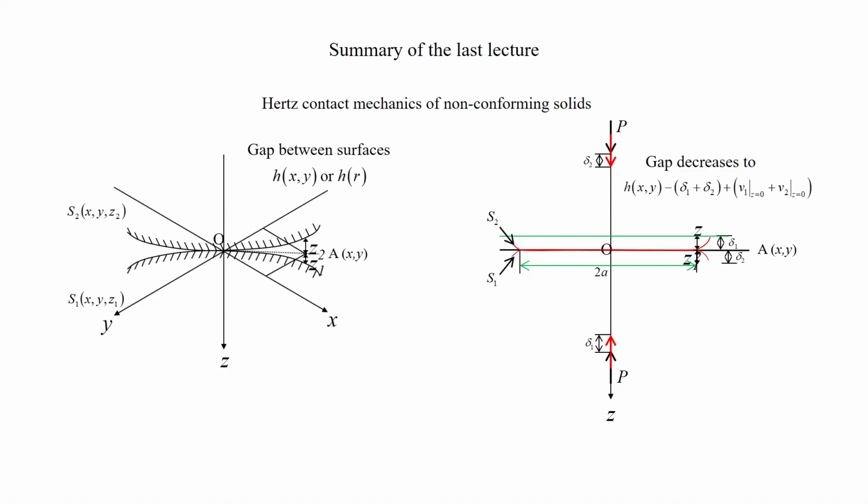In the last lecture we talked about Hertz contact mechanics, and today I will briefly recapitulate what we spoke about yesterday in the last class, and then we will discuss some ideas about surface energy and adhesion and surface interfacial energy. So, in a sense, in the last class we talked about contact of two surfaces which are two solids,